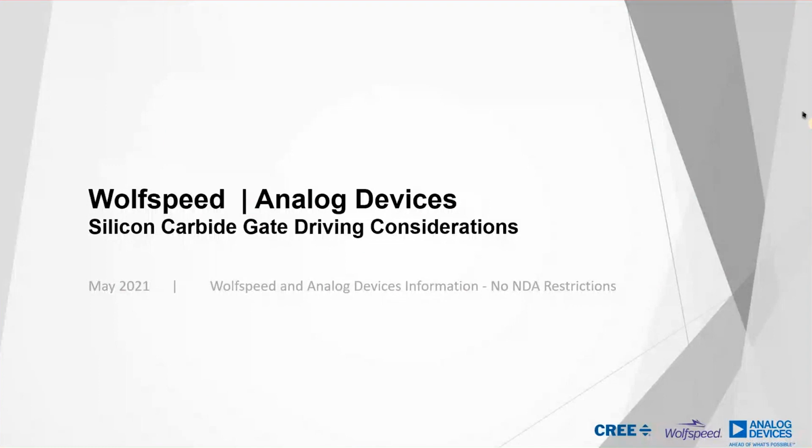Today we're going to talk with you about some of the most important and frequently asked topics when it comes to designing with silicon carbide. The faster switching speeds of silicon carbide MOSFETs compared to silicon FETs and IGBTs is one of the main benefits of using them, because it enables more efficient and power dense designs. However, these higher speeds impact other aspects of the design, and those aspects become much more critical, including gate drive, short circuit protection, and circuit parasitics. So today we're going to take a look at these topics and provide you with the information that you need to help unlock the power of silicon carbide in your designs.